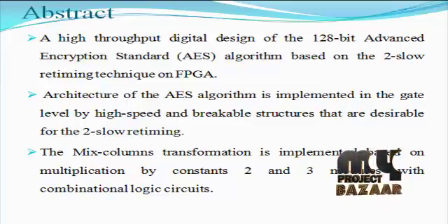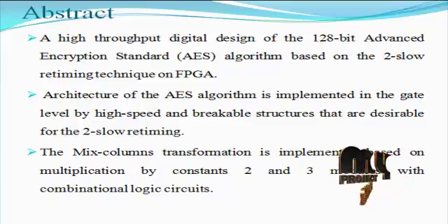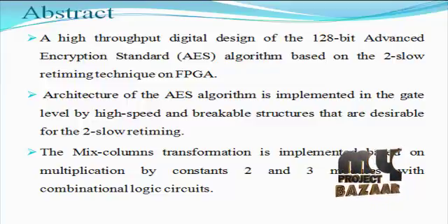It can enhance designs with feedback loops and automatically rebalance the registers in the design. C-slow retiming can break the critical path of the design into finer pieces to improve the throughput of the design. The complexity of C-slow retiming on FPGA is to find the best register allocation in the data path of the design, so that by increasing the number of registers and reallocating them to balance the AES architecture, the critical path is optimally pipelined and improved.